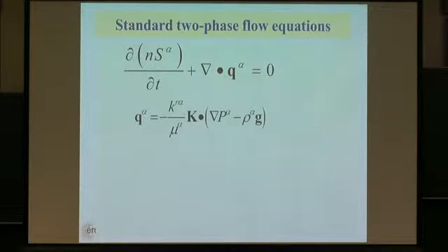And that's what I'm going to show. So these are the equations. You have seen this. This is the mass balance if the mass density is constant for each phase. So you write this twice, for the oil or water, or as I say, the wetting phase and the non-wetting phase. So you've got two equations here. This one also, Darcy's law in pressure form.